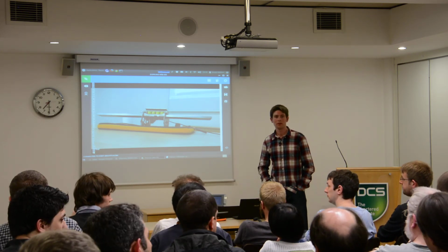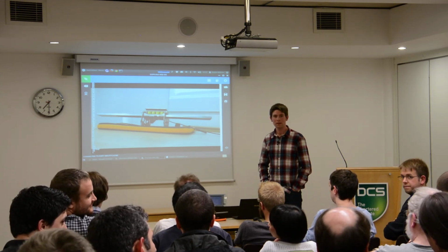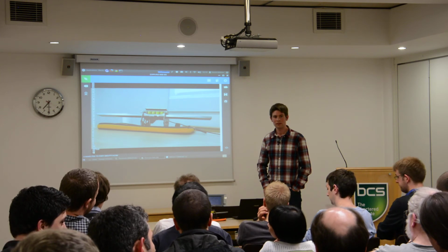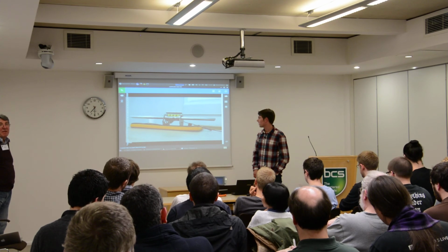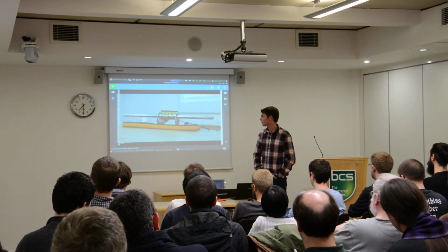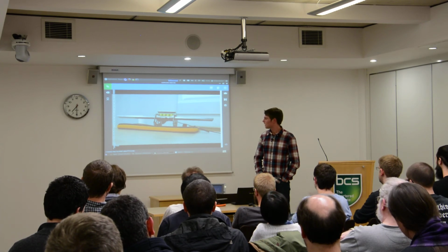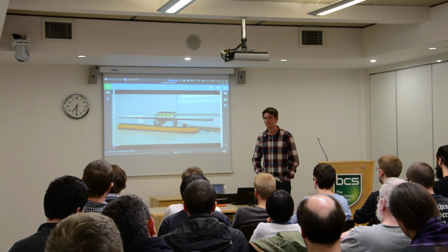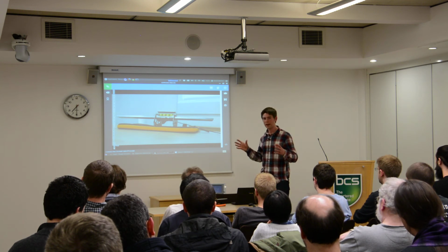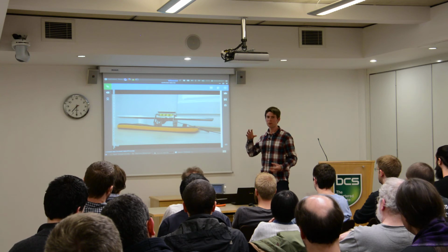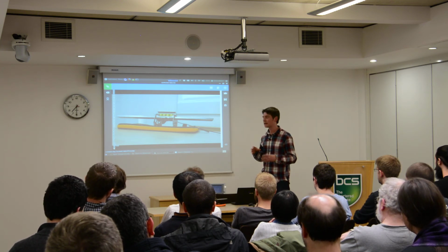How much user code can you get in a 48K part? I find when I'm programming on these things, I run out of space because I end up with too many strings. Well, it's probably 36 kilobytes of code you could get in, but because it's storing it all in one area, if you write lots of code and don't want to use very much variable space, that's fine. It shifts dynamically.